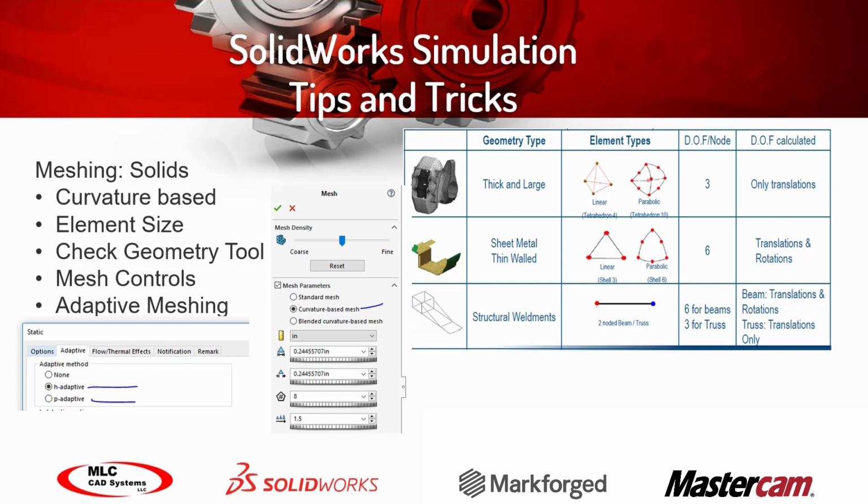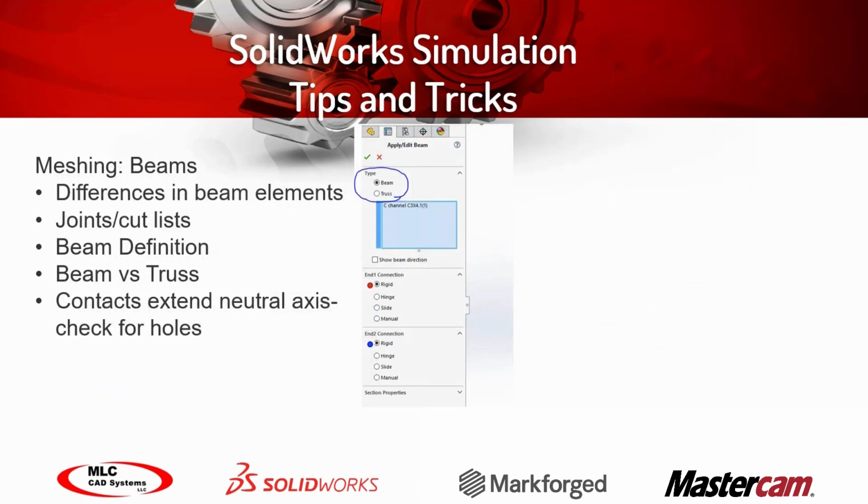Some other things that you could take advantage of with respect to meshing would be the adaptive meshing techniques. The adaptive mesh has two types, H or P adaptive. Those will only apply to solid elements. As you saw me do in the case as well, I always suggest starting off using curvature based, and kind of a rule of thumb, at least for one component, if you're doing an assembly, the maximum element size for that component would be, if it's got a uniform thickness, just half the thickness. That's what I typically start as my element size. You can always use the check geometry tool, use any mesh controls to do a localized mesh like we just did, and as I mentioned, the adaptive meshing.